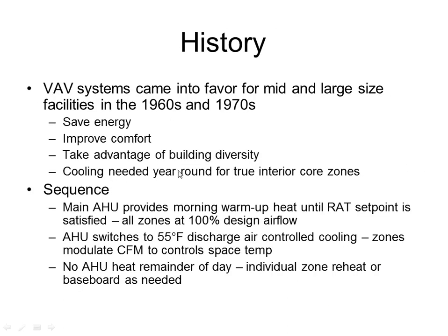First, we're going to talk about a little bit of history and VAV systems. Not exactly the topic, but a very related topic. So VAV systems began in the 60s and 70s. The point was to save energy, improve comfort, and control buildings that were a little bit more diverse, with multiple zones. And the purpose of VAV, which I want to stress today with the difference between VAV and VVT, is VAV systems are when there is a cooling load all year round. Cooling is needed 364 days a year. That is a huge difference between VAV and VVT here.